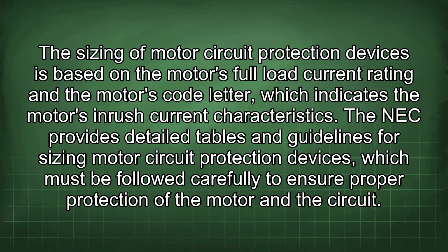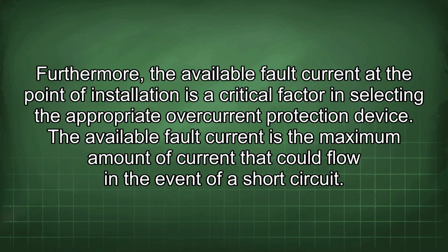The NEC provides detailed tables and guidelines for sizing motor circuit protection devices, which must be followed carefully to ensure proper protection of the motor and the circuit. Furthermore, the available fault current at the point of installation is a critical factor in selecting the appropriate overcurrent protection device. The available fault current is the maximum amount of current that could flow in the event of a short